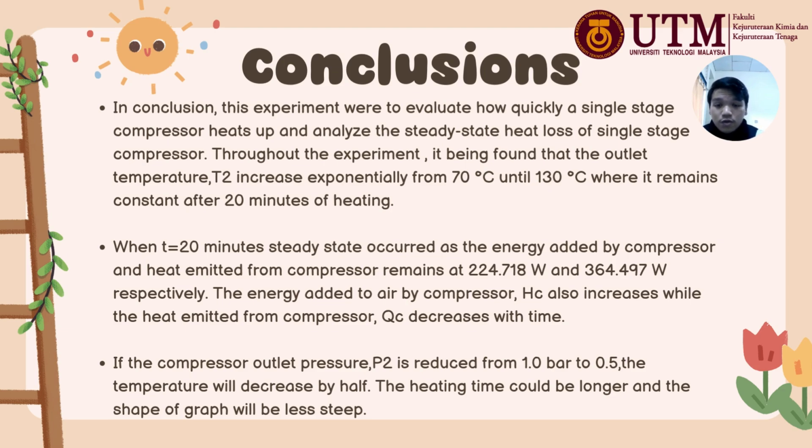When t equals 20 minutes, steady state occurred as the energy added by the compressor and the heat emitted from the compressor remain at 224.718 watt and 364.497 watt respectively. The energy added to air by the compressor, which is Hc, also increases while the heat emitted from the compressor, which is Qc, decreases with time.